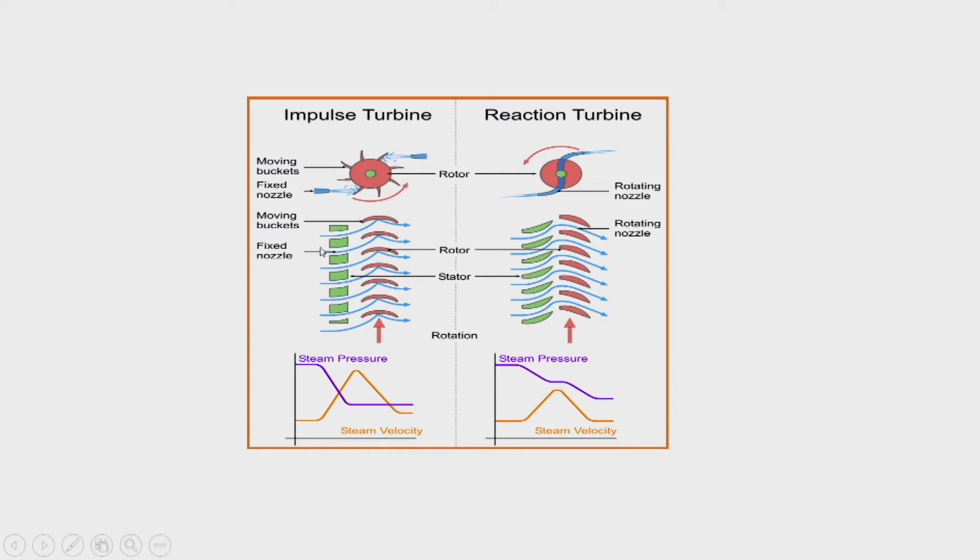In the case of an impulse turbine, the flow after coming out of the nozzle will directly impact the turbine blade, as we would see in hydro turbines. In hydro turbines, the water jet impacts the blade and imparts its energy, and then the water turbine rotates. Same thing in a gas turbine. Here we expect the flow to impart its force on the blade, and as an outcome of that force, the blade would rotate.